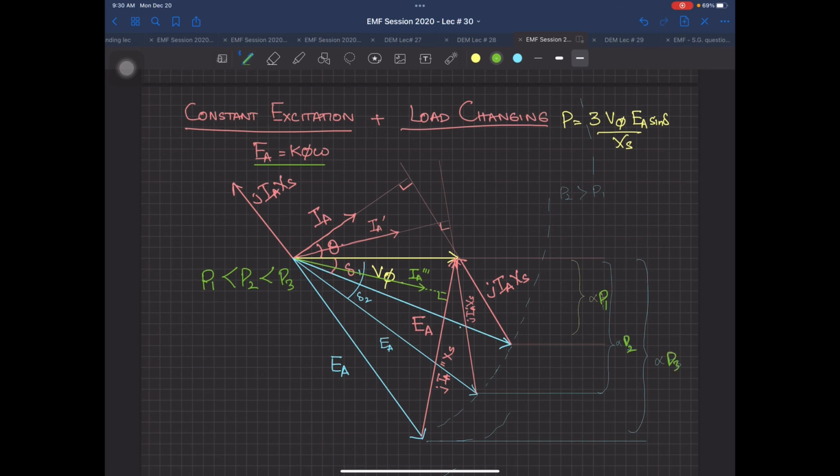And whenever you are asked to draw this phasor diagram in the exam, please draw at least, I have drawn 3 over here, at least 4 phasor diagrams embedded on it, which means 2 are leading, 1 on unity power factor, and the 4th one over here. You can draw the 4th one over here, which means I am asking about this diagram up till this point, and then this one over here as EA, and then your IA over there.